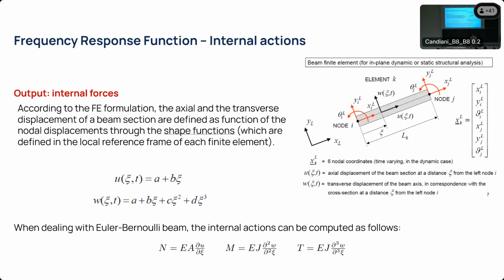We know that we are able to express the displacement of a node using the shape functions. We know that the shape functions depend on a set of polynomials, and the coefficients of those polynomials depend on the relative position of the various extremity nodes, plus what we call the running coordinate, that xi parameter that we use to run throughout the length of the element.